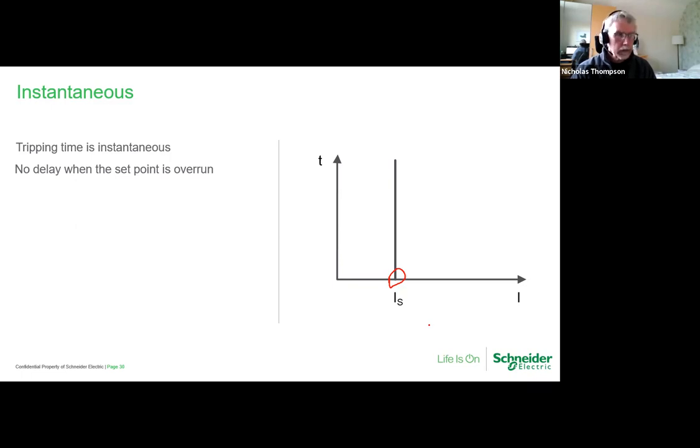But what you don't want is, if they cause a fault on the overhead line, you don't want the recloser to go through its cycle of trip, close, trip, close, trip, close. So one of the functions within the control cubicle of the recloser is live line or hot glove working. That does two things. One, it disables the auto reclose cycle, and two, it will lower the protection settings to probably its bare minimum, and then it may go to instantaneous, but that would be for the planners to decide.